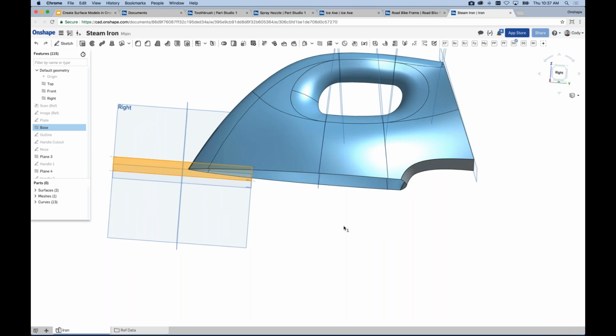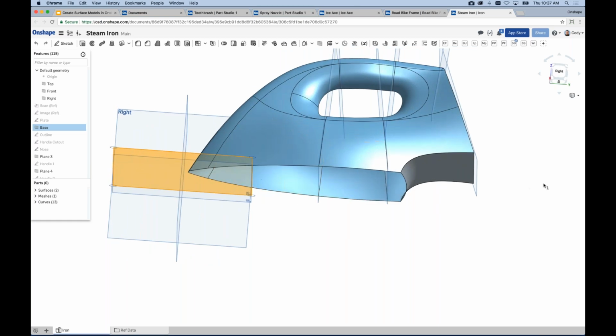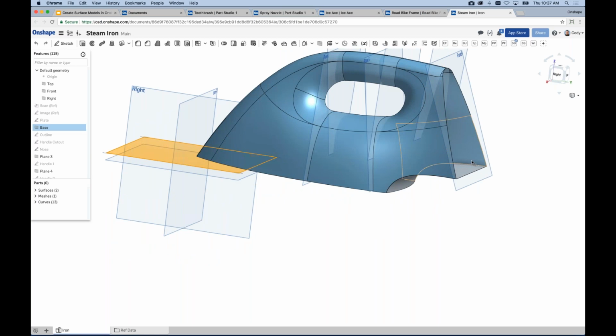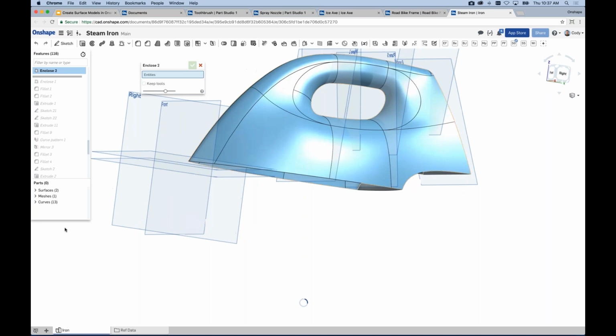So a tip, you don't necessarily have to go through all the effort. I know there are many users who still will. They will still create the fill surface here and the fill surface here, and they'll make sure they have one enclosed surface, and that's fine. But you don't have to. I can go to the enclose command. You can see it just to the right of Loft under thicken. You'll see enclose, and you can select a combination of entities that make up an enclosed volume.